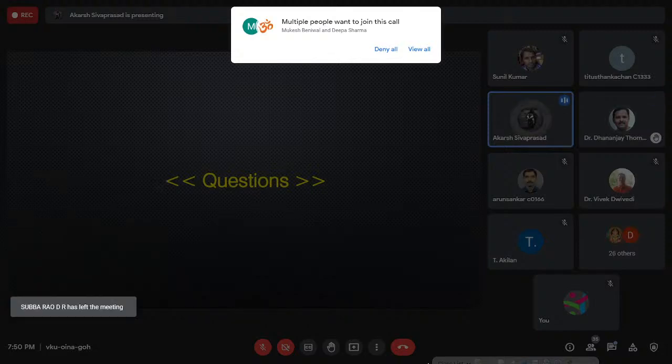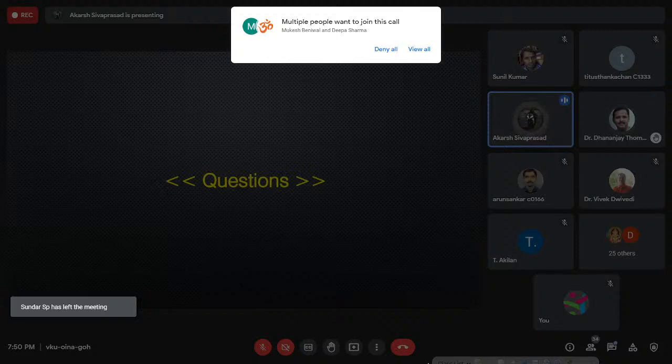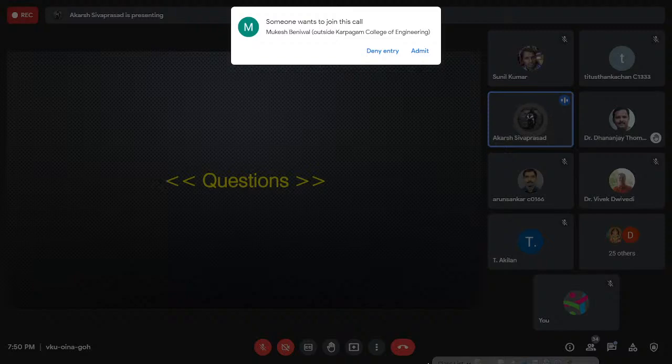Say you print a dog bone on an FDM. You can print the dog bone in three different ways: flat, on the side, or vertical. Depending on where your layers are oriented, the strength is going to vary, because if you test along the layer lines, it will yield much earlier compared to the same dog bone printed flat. The layer lines will act opposite to your tensile pulling. So it varies a lot depending on the orientation of the part and also the technology.